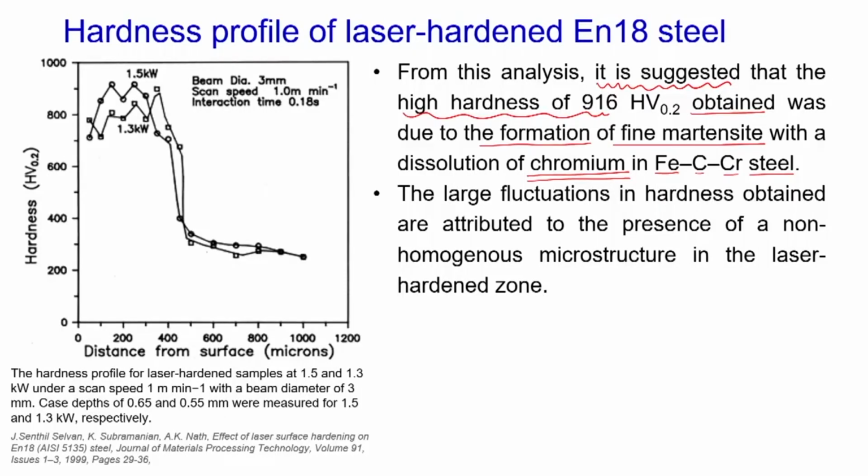We also noticed that there are large fluctuations in the hardness obtained, and it is attributed to the presence of non-homogeneous microstructure in the laser hardened zone.